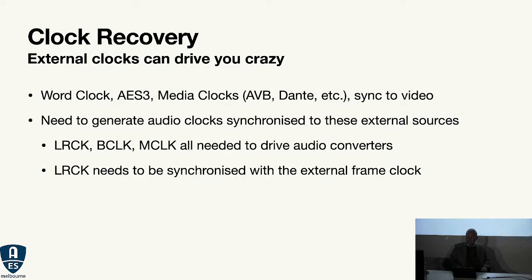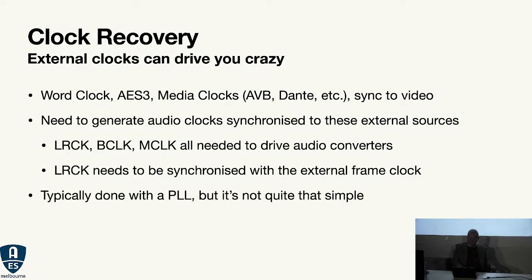One little extra thing you need to keep in mind is that the LR clock that you're using internally has to stay synchronous to the LR clock from your outside sync source. Otherwise your samples are no longer lined up properly and you get garbage. Usually this is done with a PLL. And you'd think, I run my word clock into a PLL, multiply it up, and I get my M clock, and everything's great.